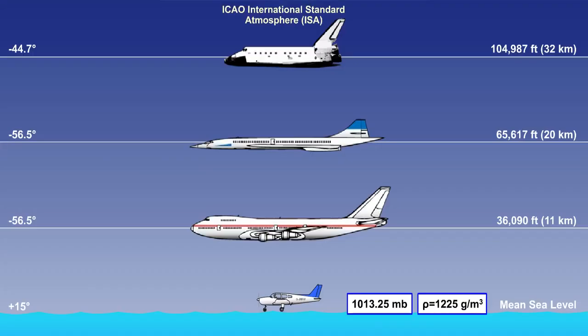Before we move on to looking at how the altimeter works, something that will be apparent if we think about it is that if the altimeter is calibrated to ISA conditions, the altimeter can only indicate the correct altitude where ISA conditions exist. And as we have seen, atmospheric conditions vary considerably. The lesson on altimeter pressure settings deals with how we overcome this problem.